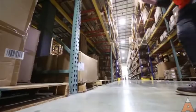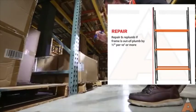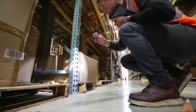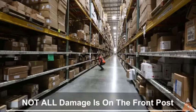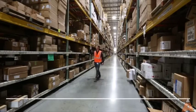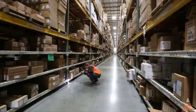If the frame is too far out of plumb by more than ½ inch per 10 feet of height, it needs to be unloaded and replumbed. This is the case for both front to back and side to side. Note, although most impacts occur on the front post, it is important to inspect the entire upright for damage and to also look for consistent damage, which can prove to be more serious.